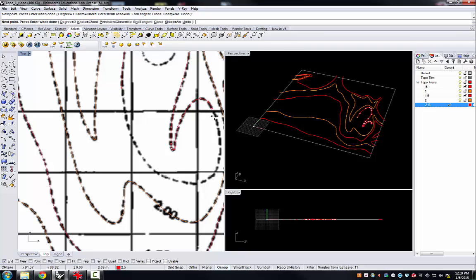And now that we've come out of that sharp curved area, many fewer points are needed to get a smooth curve to trace this topo line. If you get a point that you don't like very well, like the one I just had there, you can hit Control Z and it will just take away the previous point, and you get a chance to redo that one. Which is important to keep in mind, so that you don't have to abandon all the clicking you've done and start over if you want to just undo something that didn't work so well.